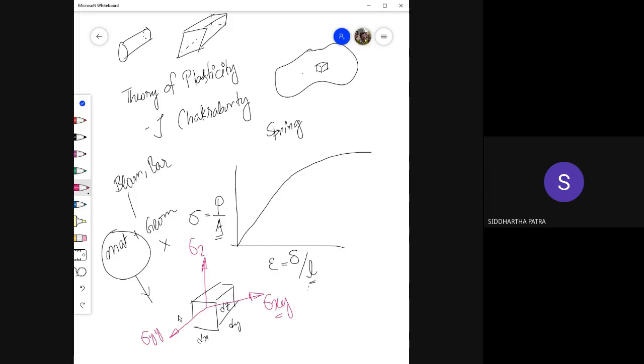But the thing is, what we see as stress and strain are the manifestation. You apply a given amount of strain in different directions and you get different sets of stresses, or you apply different sets of stresses and you get different sets of strains. Now I'm not going into that debate that stress is an internal response, and what we measure is an external force.